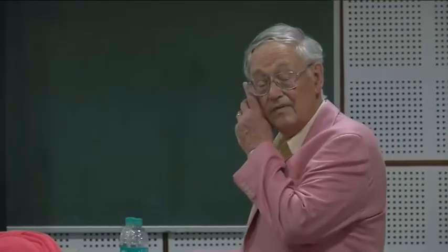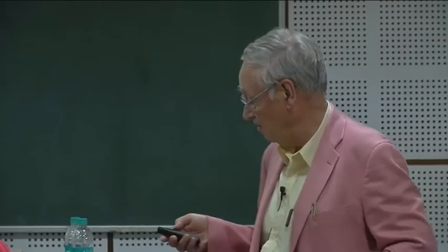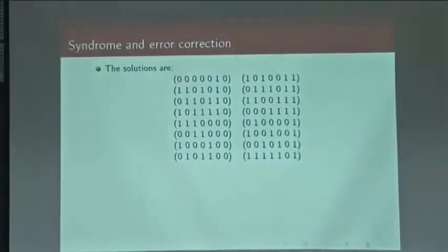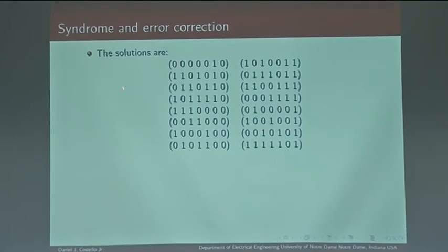Now, the maximum likelihood decoding rule says that we want to find the error pattern in the list which has the lowest weight. These could all give this syndrome. What's the one in the list with the lowest weight? Well, here's one right here with weight only 1. The others look like they all have higher weights. So this is a unique lowest weight error pattern in this case, and it is going to be our most likely candidate.